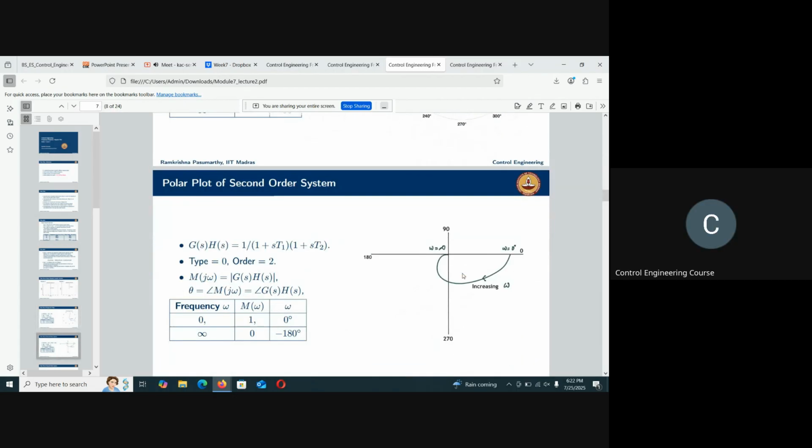Now let's do it for a second order system. In a second order system, you have two time constants. Assume both are real poles, not complex conjugate. So you put s equal to j omega, you get 1 by 1 plus j omega T1 into 1 plus j omega T2. Again, when omega equal to 0, you start at the same point here. But as omega increases, what happens is...